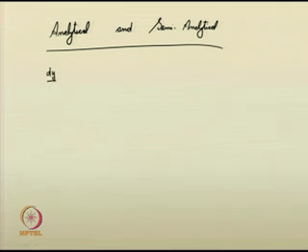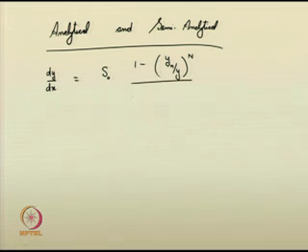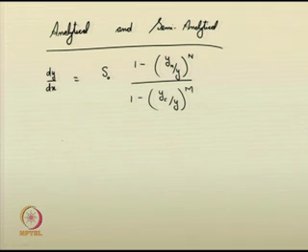So, your governing dynamic equation, if I write it in terms of depth of flow, involves y c by y whole to the power of m, where n and m are hydraulic exponents that you are quite aware of right now. Y n is the normal depth, y c is the critical depth.